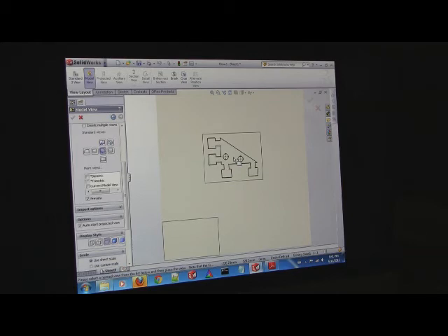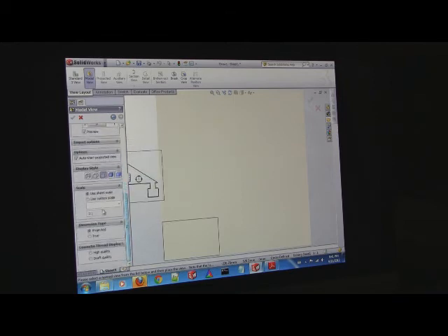Okay, now, if you're making the drawings I made a couple nights ago for you guys just to show dimensions, you want it to be reasonably sized for the page so it's not too small, it's not too big. For the laser cutter, it cuts 1-to-1. If you send me something with a weird scale, I'm going to cut it like that and then we're all going to be upset. So go down here and you see this scale here.